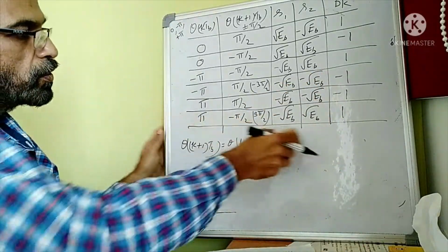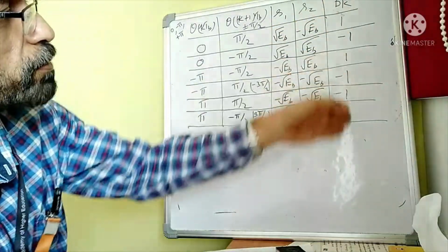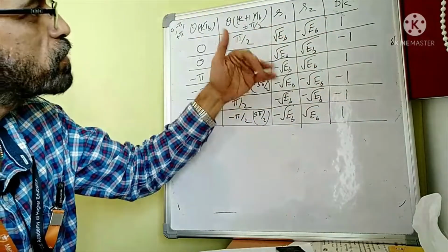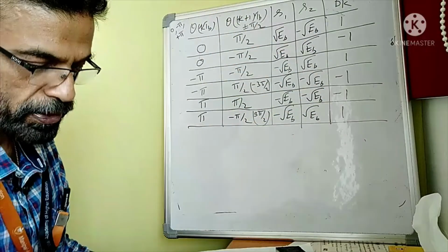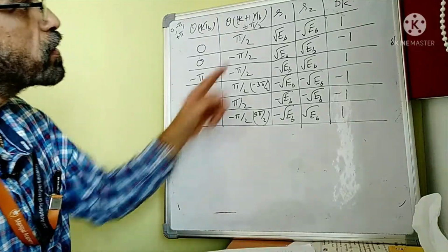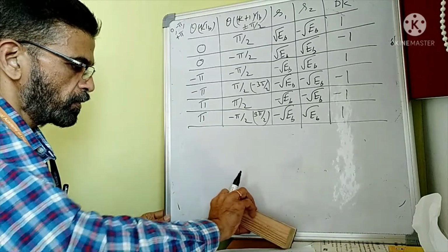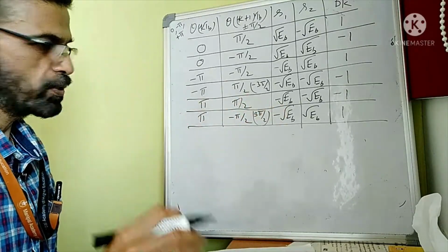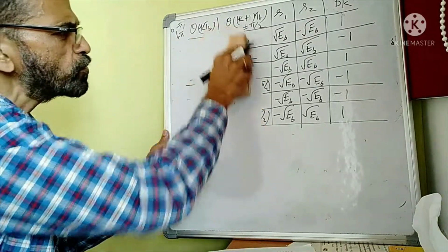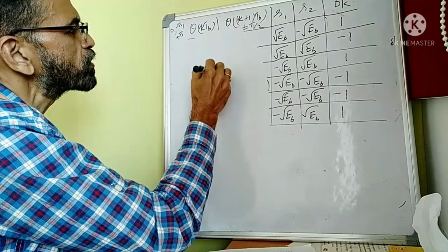So this is how the receiver is going to detect the bit transmitted in the interval k tb to k plus 1 tb. A similar thing can be formulated for the next interval and so on and so forth. Now this leads to the signal space diagram, and remember S1, S2 are the two coordinates of the signal points, assuming noise free conditions. So we are just going to draw the signal space diagram now. It is a two-dimensional signal space diagram.